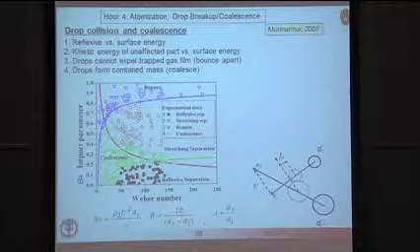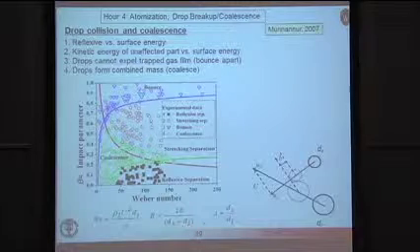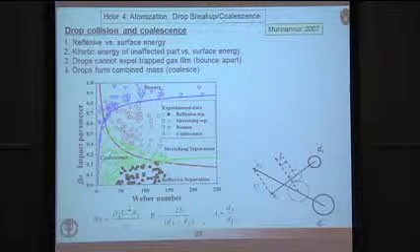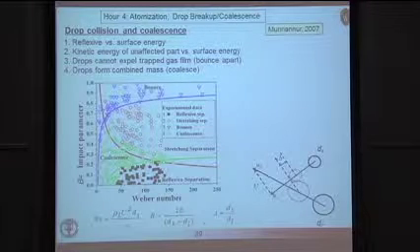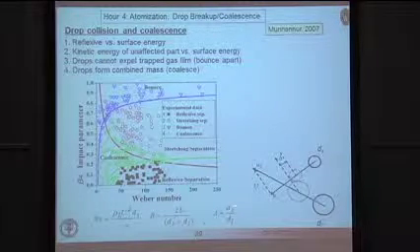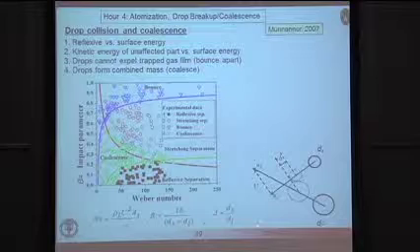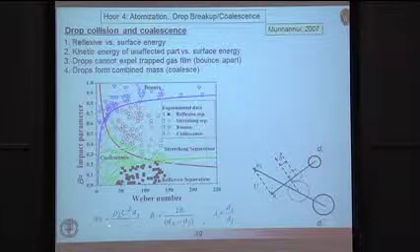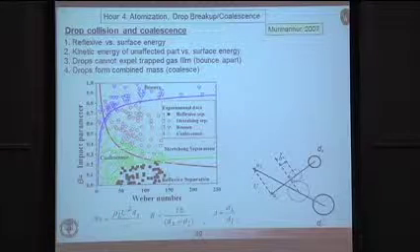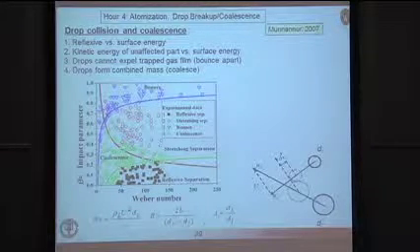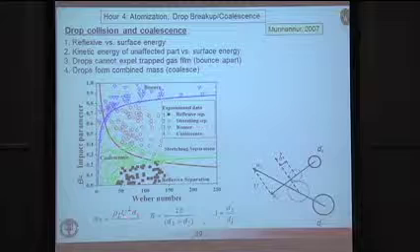It's normalized here by the sum of the diameters, or the effective radius, if you like, of the collision. Another parameter is delta, the ratio of the drop sizes of the small drops and the large drops. And then again, the Weber number, and that's what's shown on this axis. Now it's the Weber number based on the liquid phase that's important, liquid phase density.